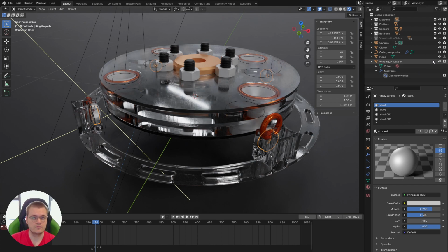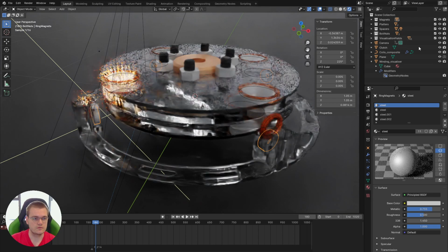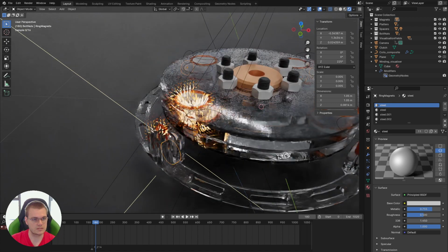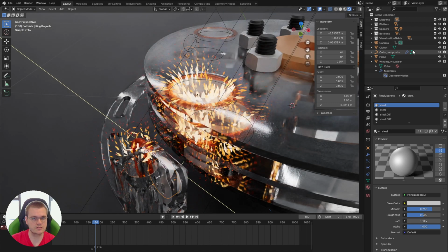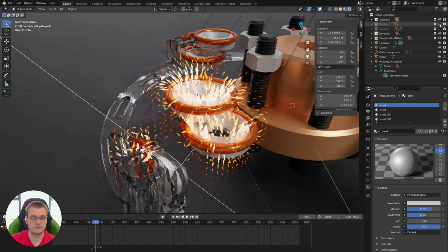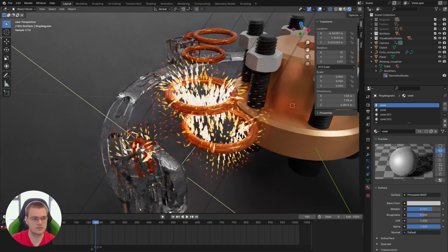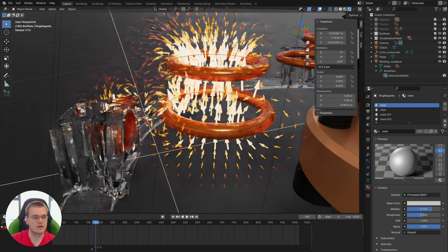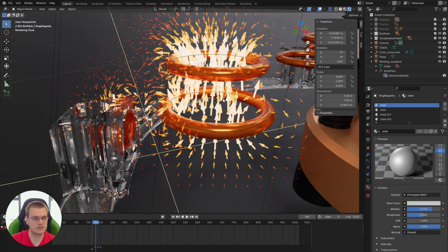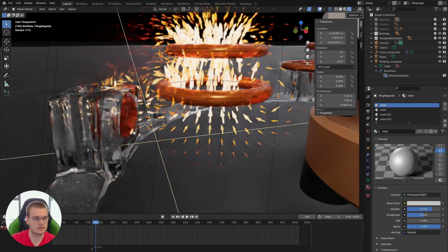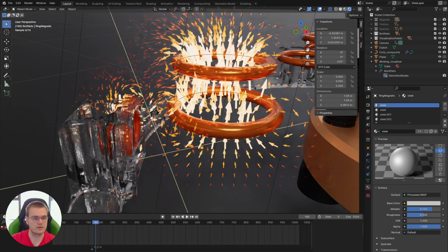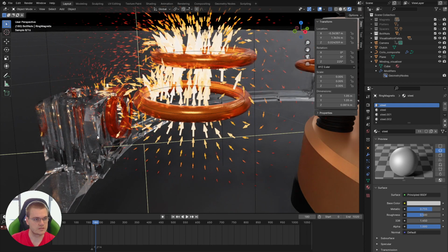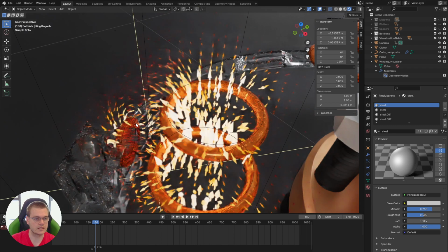We can also add visualization components to this. So I focused on one set of magnets, and here you can see some of the magnetic field lines. To more readily see that, let's turn off the other bits of geometry. Let's turn off the magnets as well. And if we zoom in a little bit here, we can actually see the magnetic coupling between the magnets inside the disk assembly and then our clutch here on the outside. So note the polarity of the magnets. These two are identical on the disk assembly. And over to the left hand side, we've got the magnetic clutch as well.